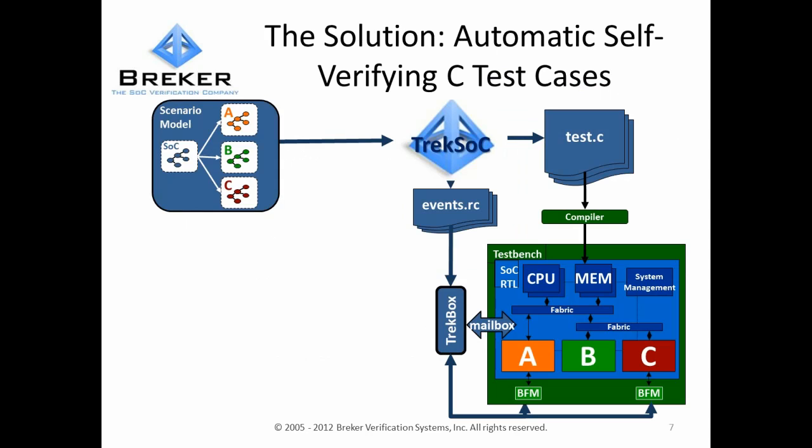At Breker, we came up with this product called Trek SoC. What Trek SoC is fundamentally a scheduler designed to test and designed to create stress tests for SoC designs. So it manages multi-threaded test cases for multiple concurrent IPs doing producer-consumer scenarios, as well as scheduling memory, scheduling I/O, scheduling the various system resources that are available, including power management.